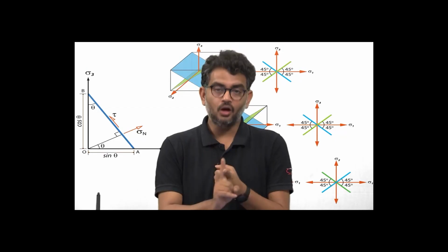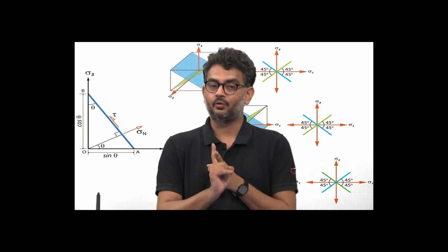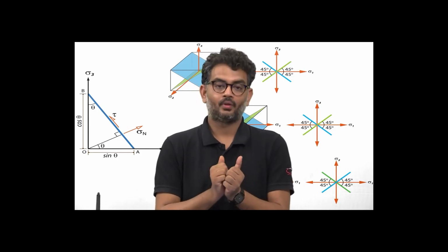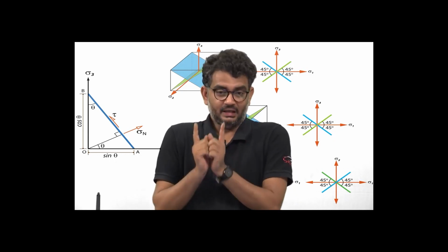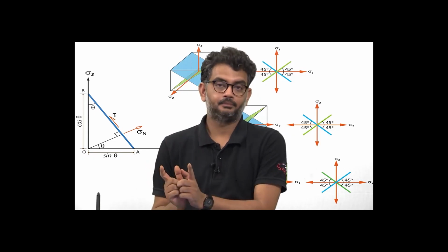So, in general, if I consider 2 dimensions, if I deform a material, there should be 2 characteristic directions along which the material lines do not change their orientations, but they only get stretched, and they get stretched equally in each and every increment of deformation.